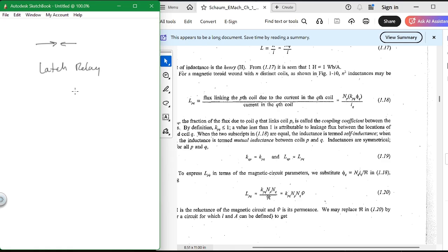So what happens when you have both of them pushing? You have this higher current in both of them. And that's why it's like two sumo wrestlers locked in a death grip, and one of them is going to give up. But in a latch circuit with a latch relay, you must design it so that you cannot turn both coils on at the same time. If you do, one is going to burn up. The weaker of the two is going to burn up. It's going to sit there with high current, not designed for high current indefinitely, and the current is going to heat it up until it burns up.